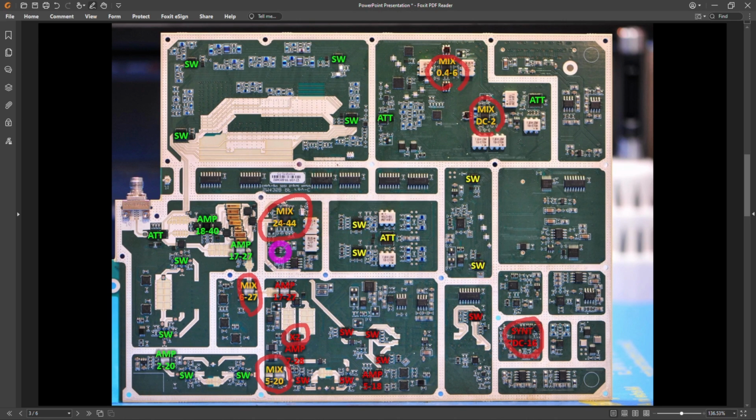In those situations, you can always do software pre-selection, but software pre-selection is slow and it's not really foolproof because it depends on how fast the signals are changing. So if you're familiar with software pre-selection, you'd know that it would slow this instrument down quite a bit. So I don't believe they're doing that in any significant way, at least.